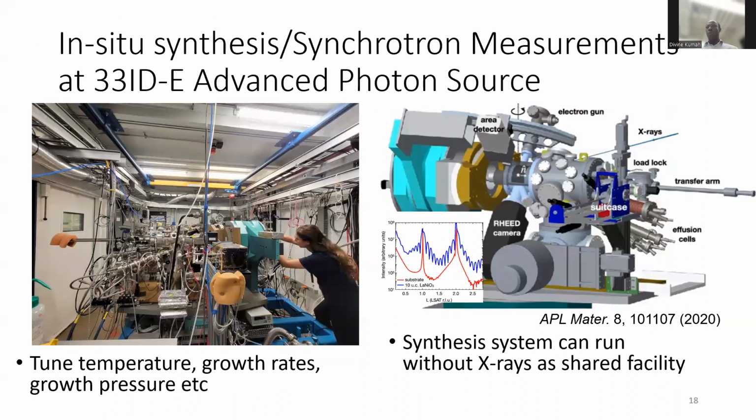All right, so we can grow these materials, we can characterize them whilst we're growing them, and those are some of the advantages of the MBE technique because it's a very slow process. It allows you to use some of these really complex tools to monitor the growth process. It allows you to also get really high purity and materials with really sharp atomically abrupt interfaces.